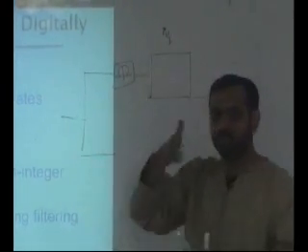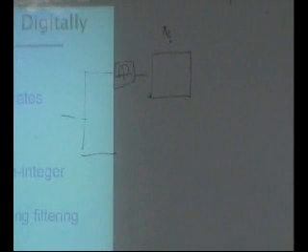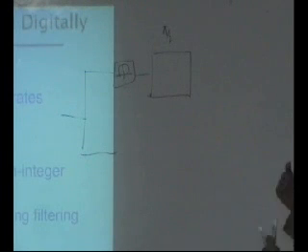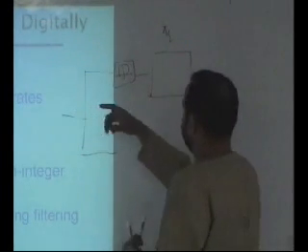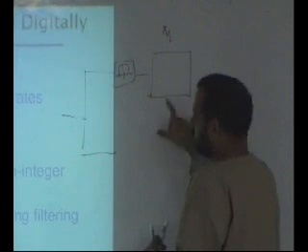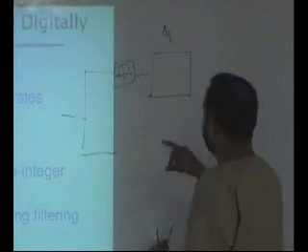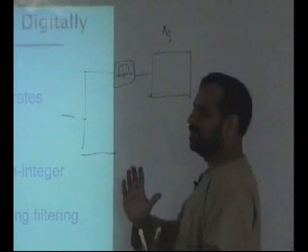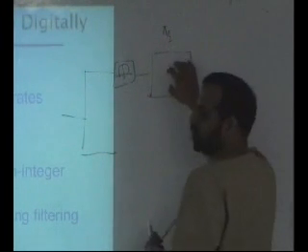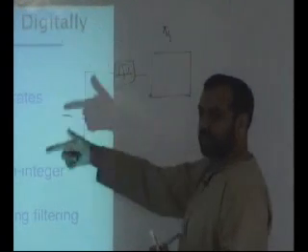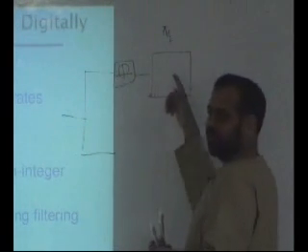in x direction and no frequency greater than pi by 2 in y direction. So you pass it, we call this a half band filter. In image processing and video processing, especially for compression, you pass it, I'll show you an example, through a low pass filter, and you pass it through a high pass filter where you have no frequencies less than pi by 2 in any direction.